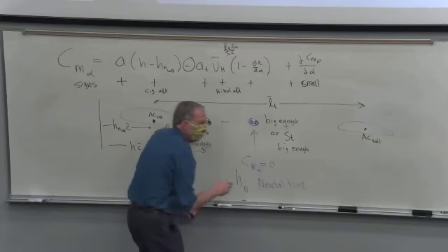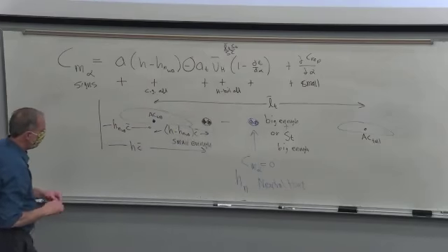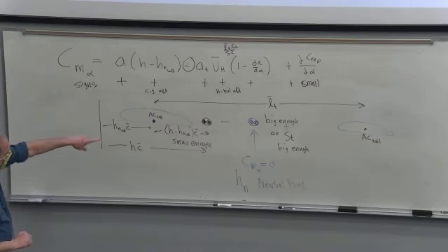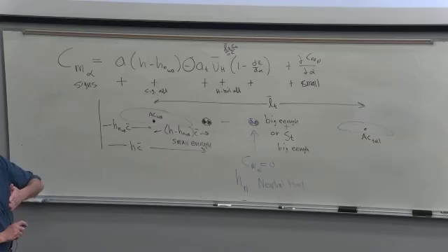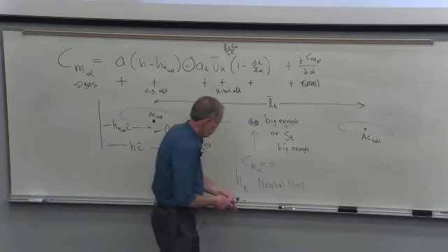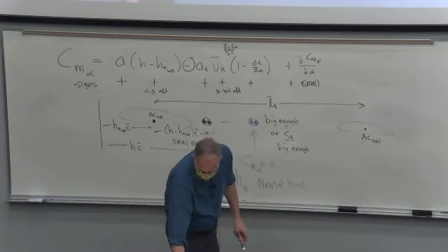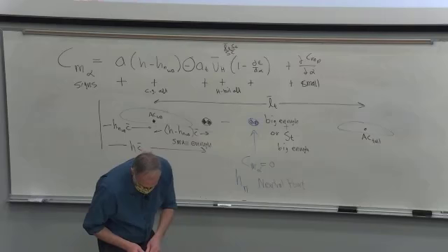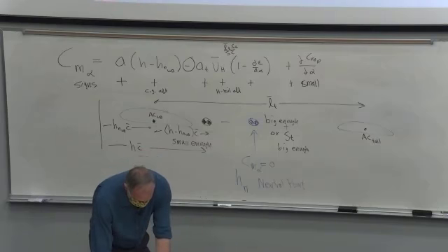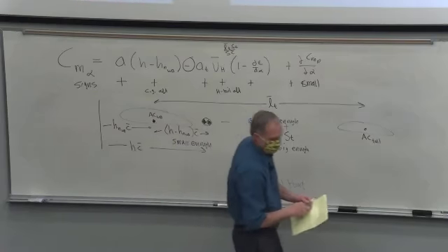And I want to write out the definition, but really what it is, it's the CG location where CM alpha is 0, or you get that borderline neutral stability between positive stability and negative stability. So this is an important definition. I hope you're writing everything down, but make sure you write this down for sure.